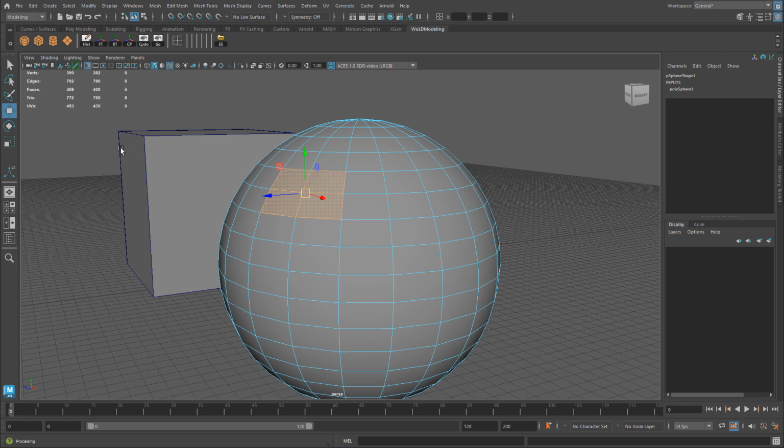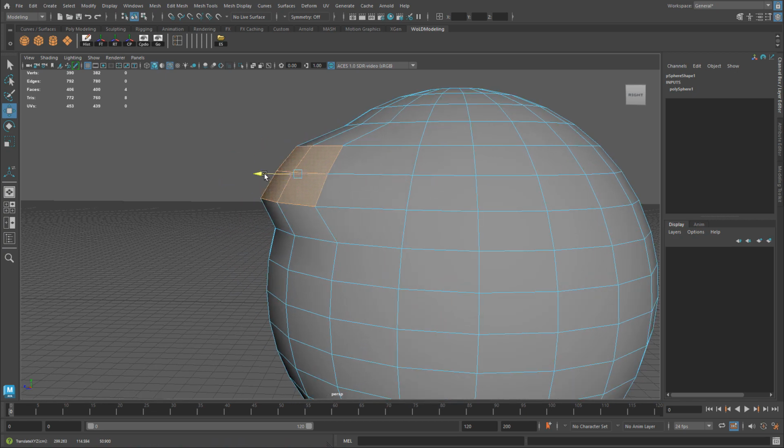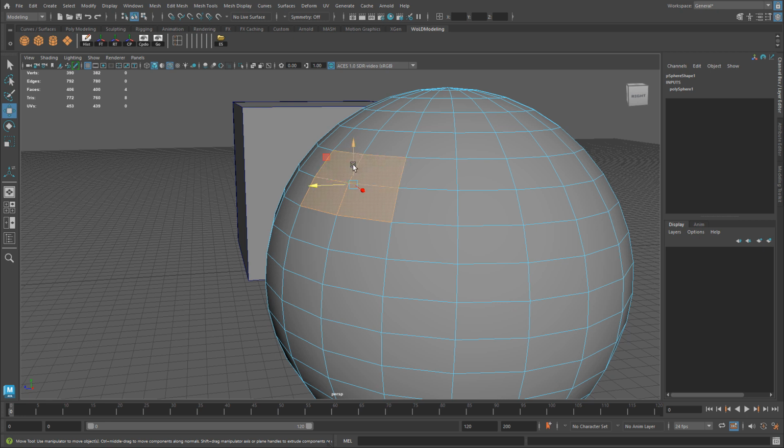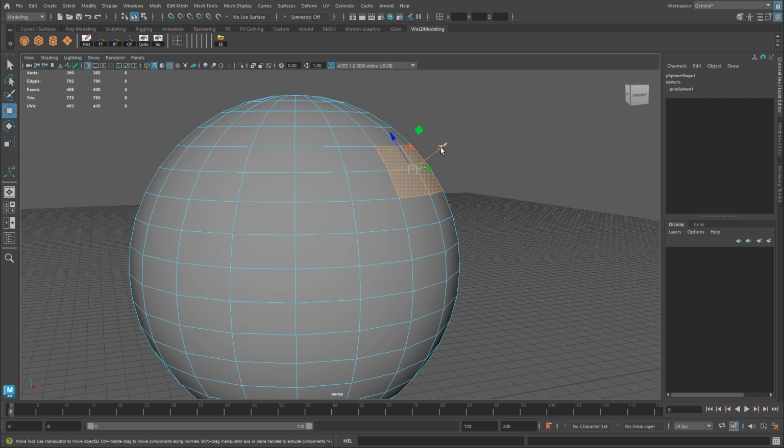So for example, if I'm in a component mode and I'm just going to quickly change it to a component itself. So right now you can see the gizmo is working in world origin. So basically I am able to move this gizmo and manipulate these faces in the world space. And I'm just going to quickly change it off to a component. And you can see that the gizmo changes. And I am manipulating these faces in a component level. Sometimes you're switching things over and working with an object and you just notice the gizmo, just what happened to my gizmo? Why doesn't it orient in the way that I expect it to on the default object? So somehow one of those selections got switched over to another axis orientation.